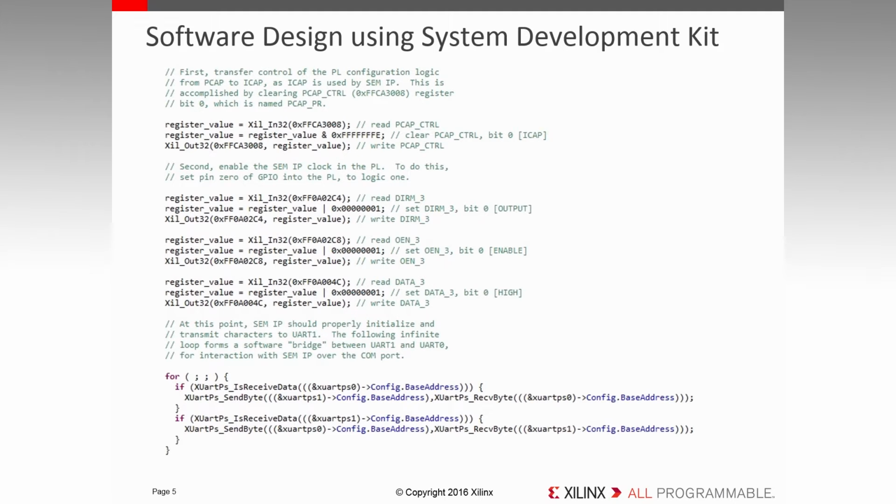I'll show you it works in just a moment, but first let me address a question I'm sure you're asking right now, which is how in the world would I apply an infinite polling loop in my design? You wouldn't. What you would do, though, is leverage the capability and features of the processing system UART, which include a receive FIFO and interrupt capability. After the startup code executes, you receive the initialization report for confirmation and then set up an interrupt to respond to data available in the UART receive FIFO.